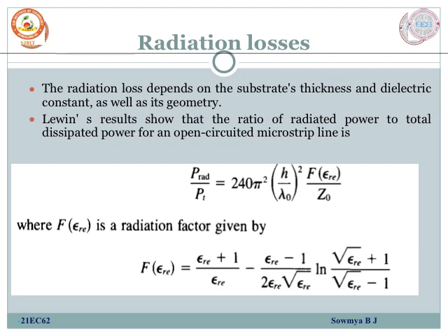Now let us discuss another type of losses called radiation losses. The radiation loss is mainly dependent on the substrate thickness, the dielectric constant as well as its geometry.